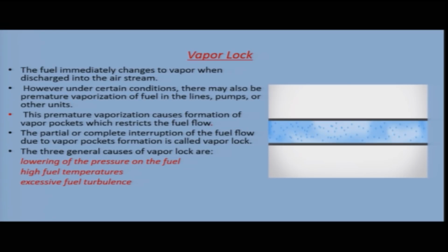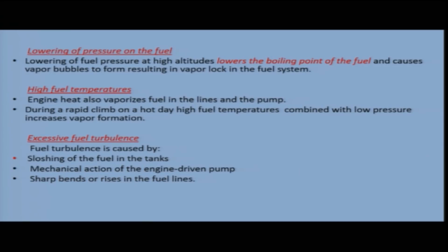The main reasons are lowering of pressure on the fuel, high fuel temperatures and excessive fuel turbulence. Because of these reasons, vapor lock formation can take place. First, lowering of pressure on the fuel. Lowering of fuel pressure at high altitudes lowers the boiling point of the fuel.